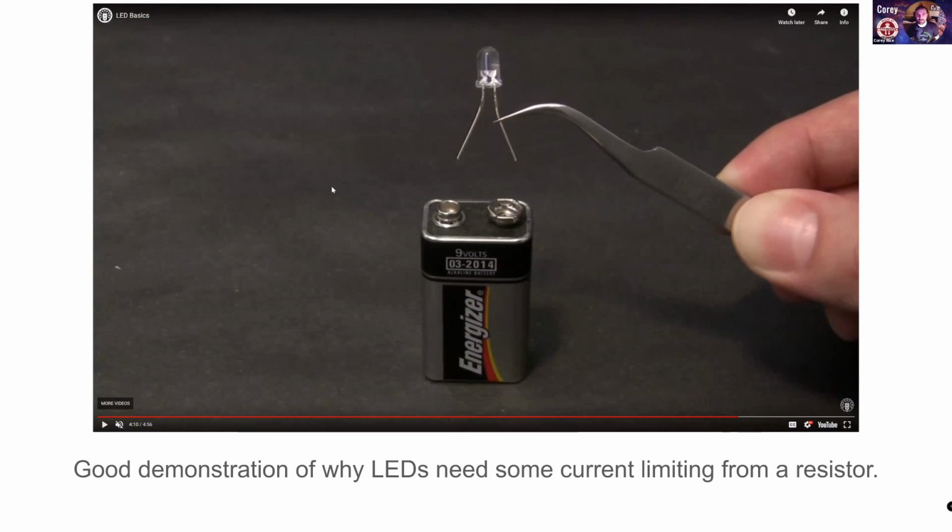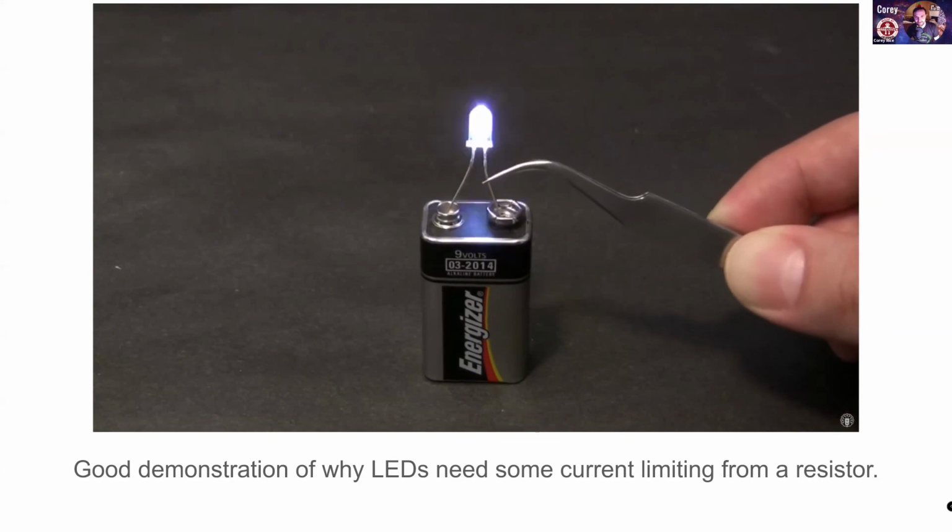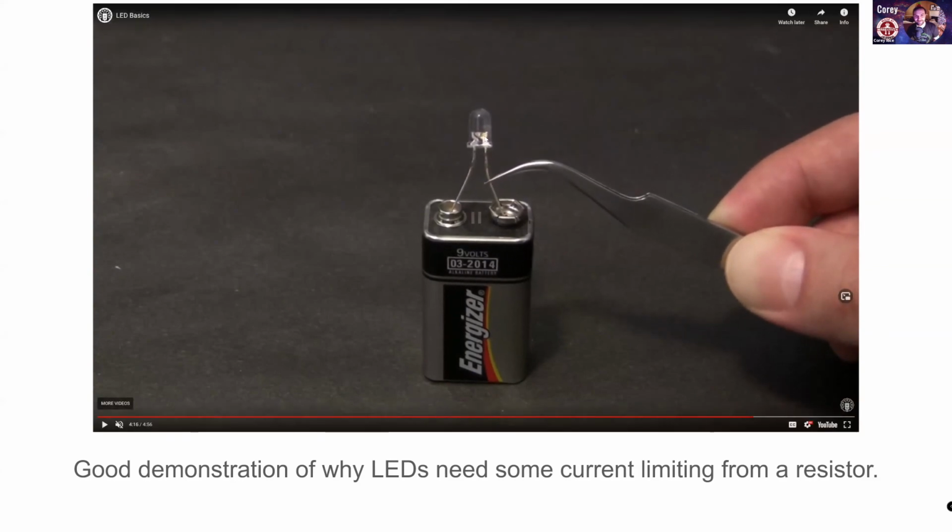So what he's about to do here is just one without a resistor attached to a 9-volt battery. This is the more common failure mode that I've seen for LEDs. And so watch, because it happens fast. Boop. And that's it. There's a little bit of brown, a little bit of charring inside, but it's super hard to see. And if you ever have one that you tried both ways and you're not sure what happened and you have no idea why, you probably burned it out and missed it, right?